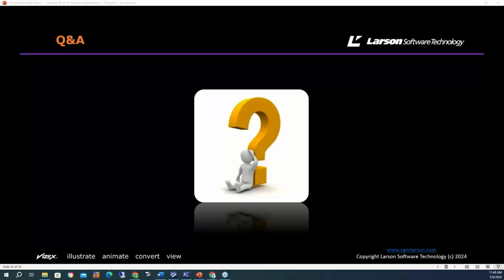Yeah, and we have the usual question about raster to vector conversion, which is almost inevitable. So we have a pretty stock answer. If your raster files are of reasonable quality, then don't turn them to vector. Use them as is and add to them. If they're poor quality, which would mean they're not really suitable either to convert from raster to vector or to use as original illustrations, then you're probably better actually recreating them.